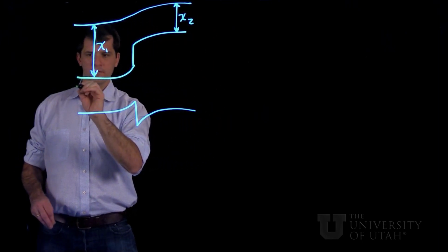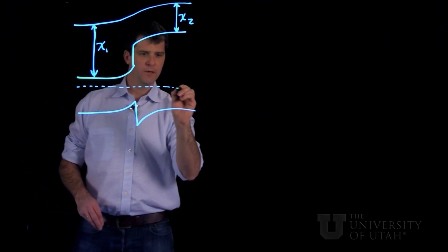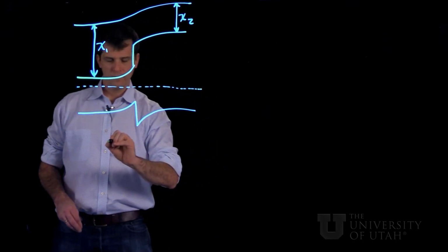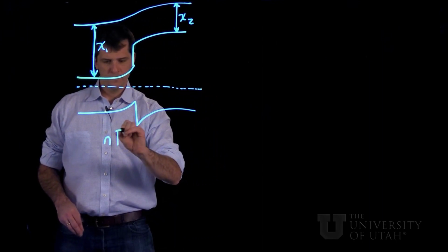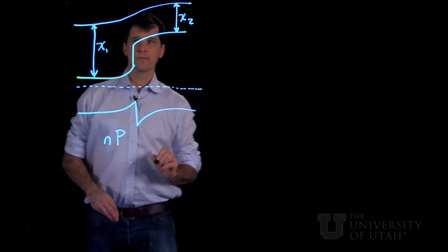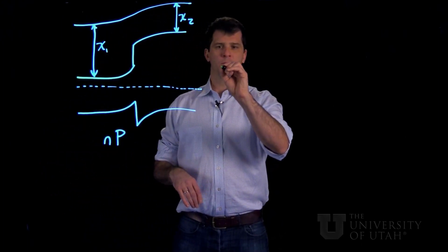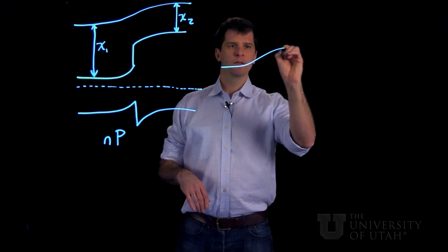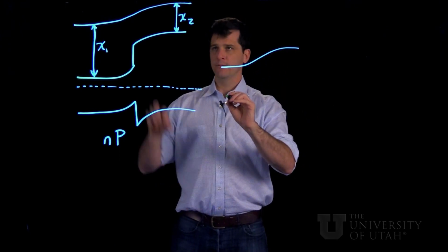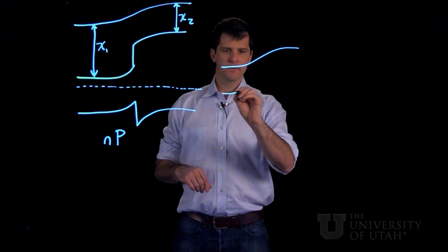And that our Fermi level is constant throughout the band diagram. So this again was for an N-P junction like this. So this is actually the same case as what happens in a PN junction, just where you have two different chi's on either side here.